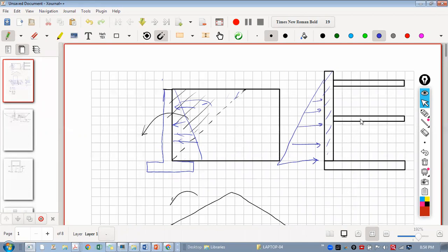This beam or slab, especially the slab, I am saying the steel should go inside the wall. That's a detailing. Detailing is very important because you are assuming a prop, so the reaction has to be transferred in this slab.